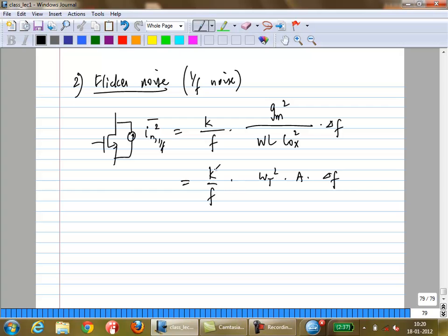So if you want to measure at lower and lower frequencies, you have to average longer and longer, which becomes more and more difficult. So what you can do is average to a point where it's practical. Okay, so what does practical mean? If you are designing a circuit, the circuit itself will tell you what DC means. It just means how long your observation averaging interval is. You can perform measurements based on where you expect to use it.